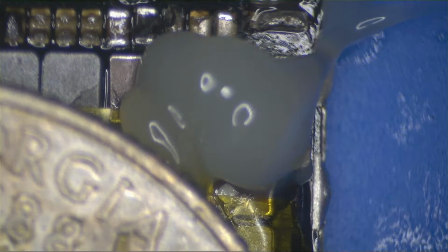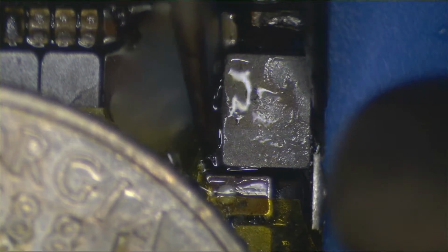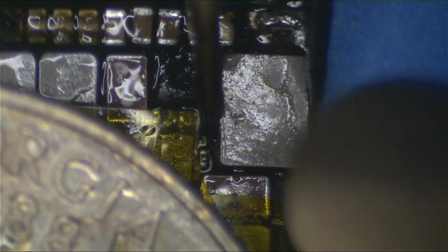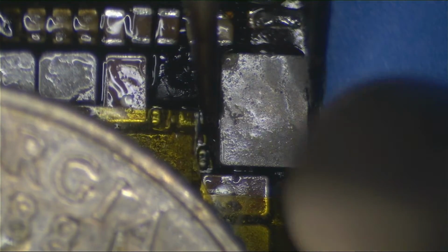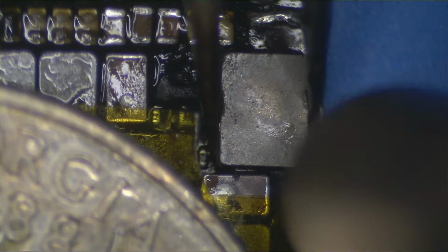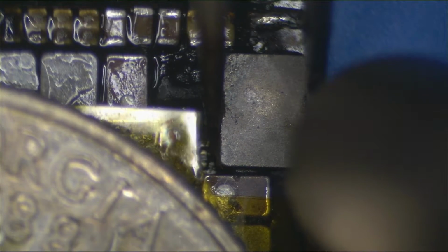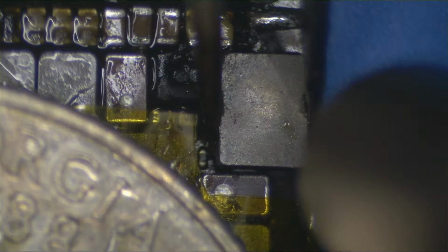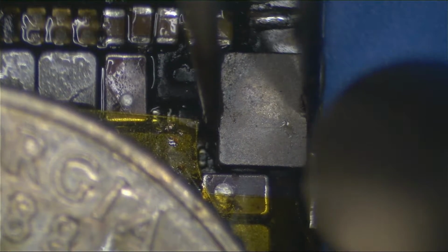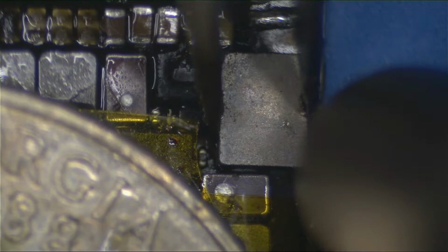So a little bit of flux on top, and I'm just going to hit it with some hot air and try to pull the coil off. Now the coil's not really going to come off in one piece because it doesn't really work that way, unfortunately. You can try to get it off in one piece, but it's not really worth the effort. The coil really just likes to disintegrate on its own. So really, all you have to do is make sure you don't pull the pads underneath. You can take it off as roughly as you want, and whether or not it comes off cleanly is really just luck. Of course, I'm doing it on video, so the chances of the coil coming off cleanly are pretty much none.